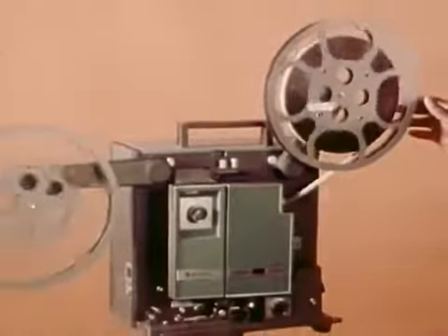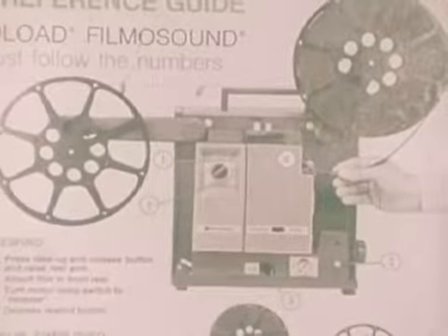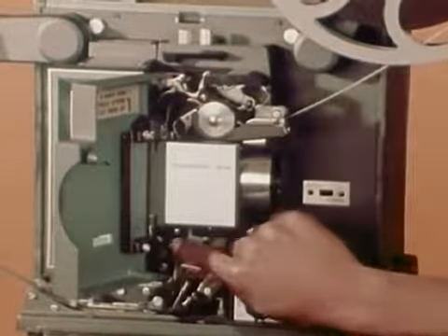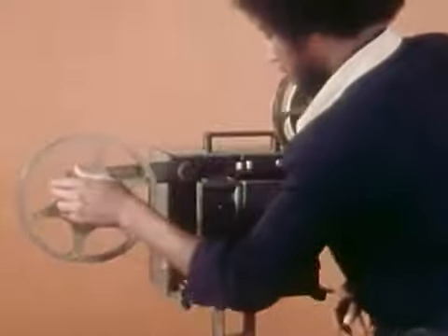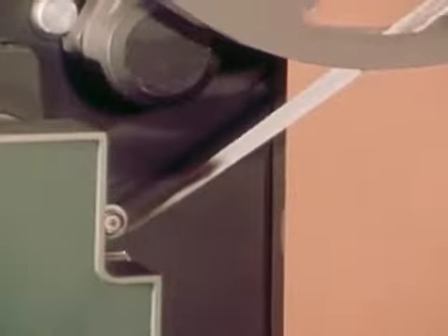Some motion picture projectors are designed to thread the film through the machine automatically and form the loops to the correct size. It is still important, however, with such machines to read their instructions carefully and to check to see that the automatic threading devices have performed properly. Films to be used in auto-thread projectors should be supplied with long leaders in case of a malfunction.